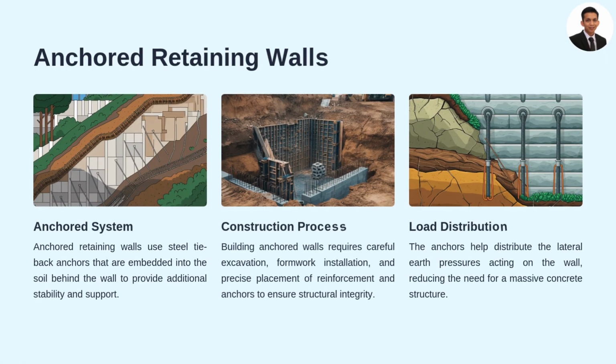Anchored retaining walls. Anchored retaining walls are designed to handle high lateral loads, often in deep excavations. Anchors or tiebacks are drilled into the soil and tensioned. These anchors counteract soil pressure, allowing for thinner walls.